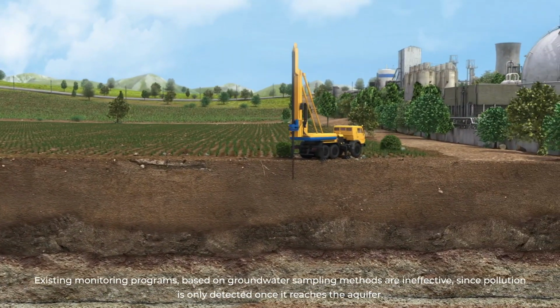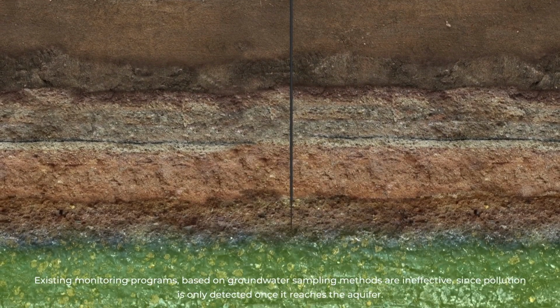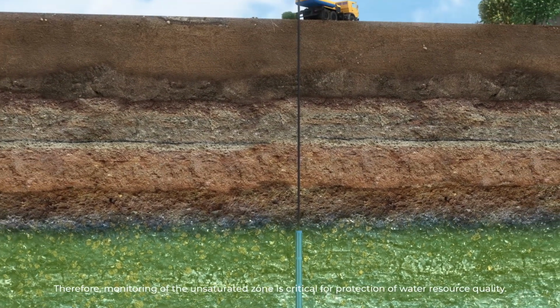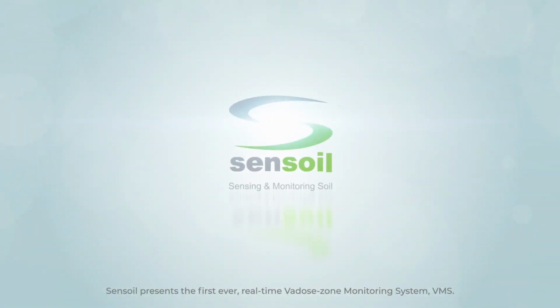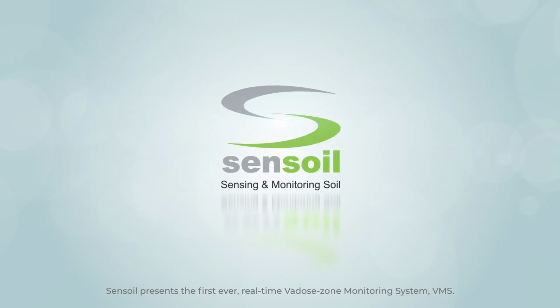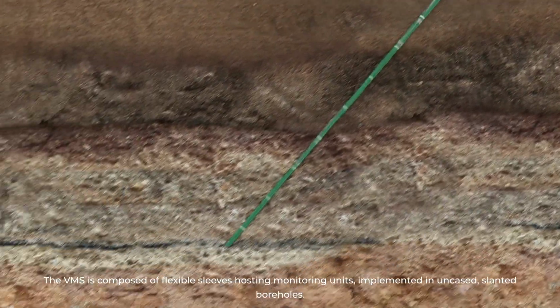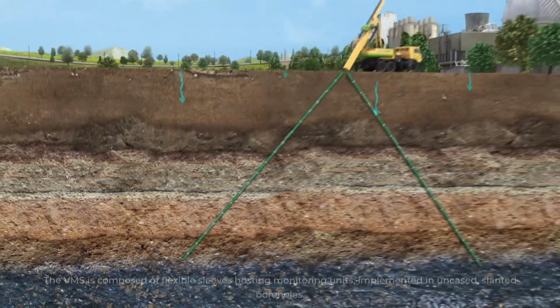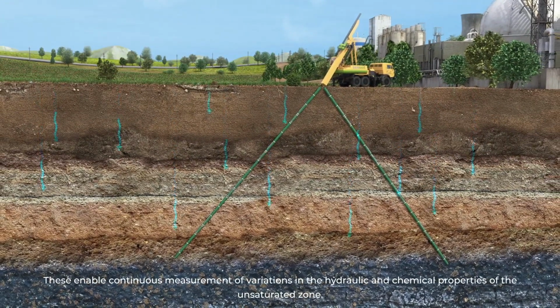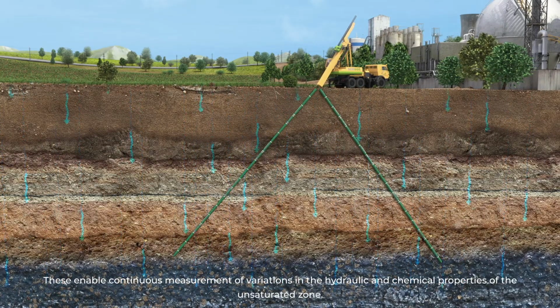Existing monitoring programs based on groundwater sampling methods are ineffective, since pollution is only detected once it reaches the aquifer. Therefore, monitoring of the unsaturated zone is critical for protection of water resource quality. Sensoil presents the first ever real-time vadose zone monitoring system, VMS. The VMS is composed of flexible sleeves hosting monitoring units, implemented in uncased, slanted boreholes. These enable continuous measurements of variations in the hydraulic and chemical properties of the unsaturated zone.